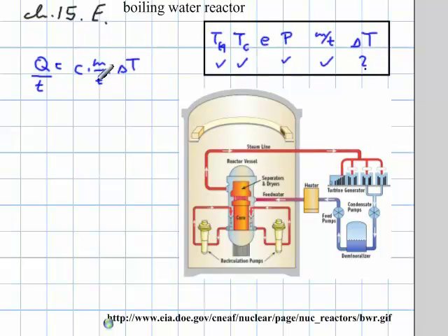So that means now I have a known here, and I have a known here, and this one here is my unknown, my variable, and this one here is kind of known as well because it's the heat that goes into the river per time unit, per second, and that one is determined from the efficiency, which we determine in a moment, and the total output, the power. Okay, so let's do the efficiency next. The efficiency is, of course, for a Carnot engine, 1 minus Tc over Th.